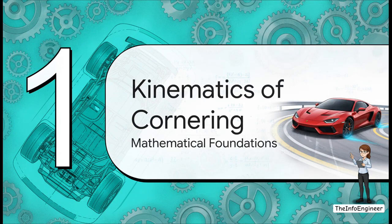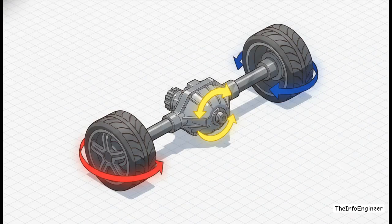Section 1. The kinematics of cornering. Let's get into the math. Let's start with the hard numbers that govern every single differential out on the road. Look at this constraint equation right here. Omega L plus omega R equals 2 times omega C. In plain English, the left and right wheel speeds have to average out to the carrier speed. It's the absolute law our drivetrain must obey.